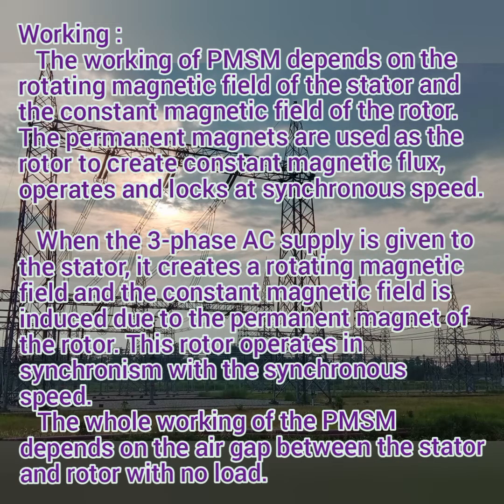Coming to the working, it depends on the rotating magnetic field of the stator and the constant magnetic field of the rotor, because the rotor has a permanent magnet, and it produces a constant magnetic flux and operates and locks at synchronous speed. So when a three phase supply is given to the stator, it creates a rotating magnetic field, and the constant magnetic field is induced in the permanent magnet of the rotor. So this motor operates in synchronism with the synchronous speed.